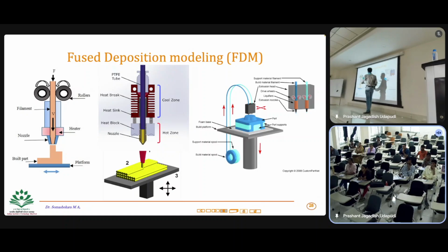Because as soon as the solid filament is coming inside, you need to melt it, right? Initially, you have the standard filament, 1.75 mm is the standard filament size. But your nozzle is not like that, and if you try to print without heating it up, it will not work, because you cannot bond the layers, or you cannot bind them together, right?